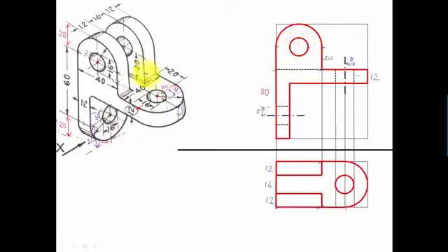Okay, the limits are, you're going to have initially an axis. Let me show that. You're going to have an axis over here passing through this point. So basically what I'm going to be doing is having an axis at a distance of say 20 millimeters from over here. This point I'm talking about is 20 millimeters from this end. So from 20 millimeters from this end, I'm going to be having an axis, something like this. So an axis for this profile also, this hole also, and for this hole also, for both of them. So I've made the axis.